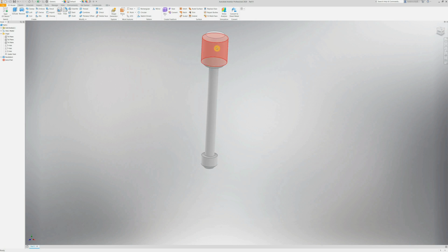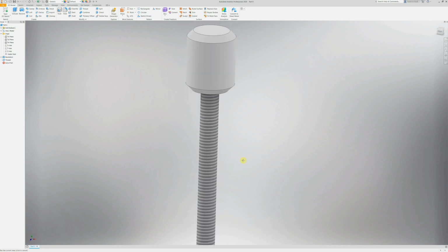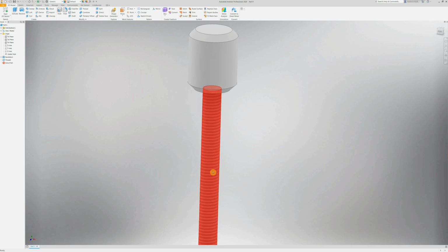So a couple of wee things more to do. We've got to put a hole up here, and we've got to put a cosmetic thread on just here. I'm just going to put the cosmetic thread on, say the word thread, and we'll make that component threaded just there. Now we do that, remember, with a cosmetic thread, because putting a real thread using the helix tool would slow the computer down dramatically. You'd be creating all these extra vertices and slowing things down, with not much real benefit. But we want to say this is a thread, so later on, when it comes to technical drawing, we'll be able to put the technical information about that thread just there. And we can adjust the settings and the types of thread and so on, but we're not bothered about that too much.